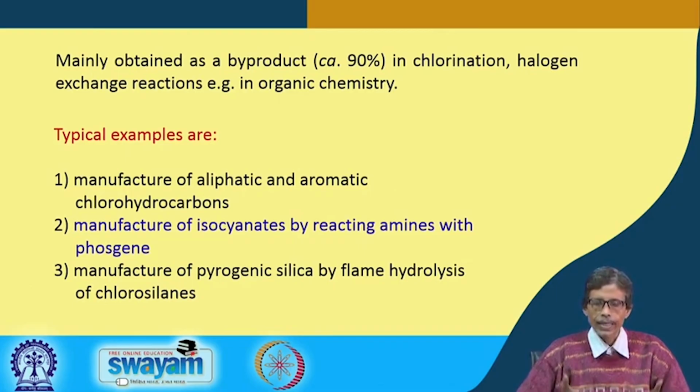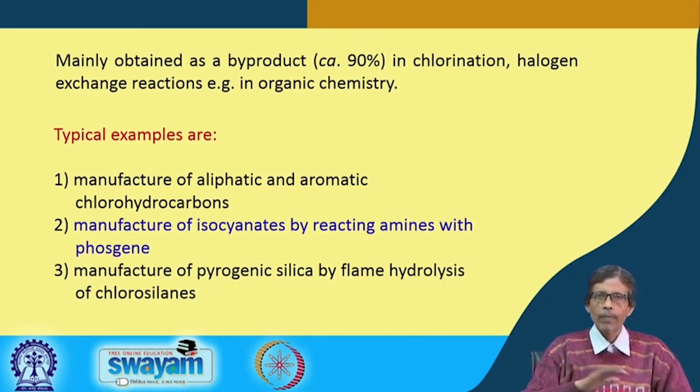Over the liquid reaction medium we have gas molecules covering it, so we should have an exit pathway above the liquid such that we can take out the byproduct HCl from that particular outlet. So we should have the typical provision of making that outlet which can take out the HCl produced as a byproduct of any kind of reaction.